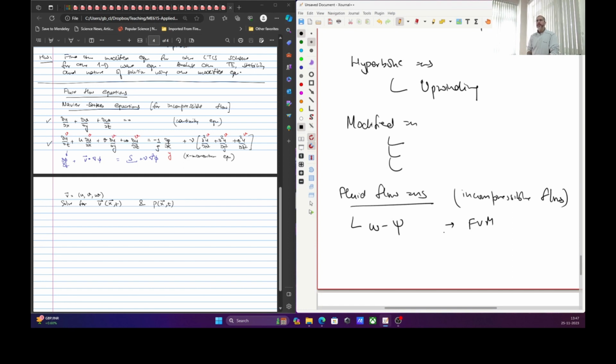That is the reason most of the solvers only work with your primitive variables u, v and p, even though dealing with this becomes much easier computation. Because implementing boundary conditions becomes quite confusing. In fact, when you would have worked with solving the lid-driven cavity, applying the top boundary condition would have been a bit tricky. Now, top boundary is like a streamline, right?